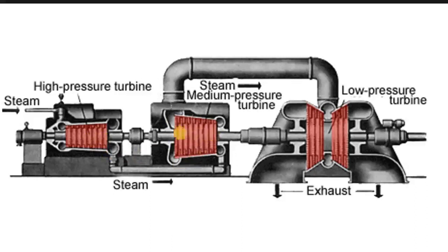So when the steam leaves this high pressure turbine, it now enters the next, intermediate pressure turbine. But before it enters the intermediate pressure turbine, this steam is sent back to the boiler to be reheated to about 550 degrees Celsius, but the pressure has now dropped to about 30 bars. It dropped from about 150 bars to about 30 bars in the impulse turbine stage. So all of the pressure is normally dropped only in the nozzle section, right?